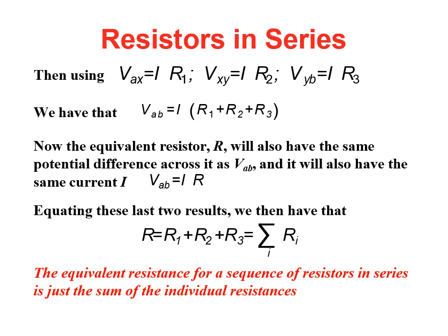So you can take I as the subject. We know that the sum of the voltage drops will equal the sum of the applied voltage. The applied voltage here is AB. So VAB equals I, the total current, times the sum of all three resistors, R1 plus R2 plus R3.